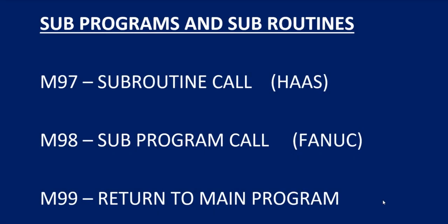In this session, I want to talk about subprograms and subroutines. I'm going to introduce new M codes, M97, M98, and M99. The M97 is basically used on a Haas machine, and that's where we call a subprogram or subroutine from within the program. An M98 is calling a subprogram outside of the main program, so you have more than one program working together. Then the M99 is always placed at the end of a subroutine or a subprogram to return back to the main. Let's see how that's done.